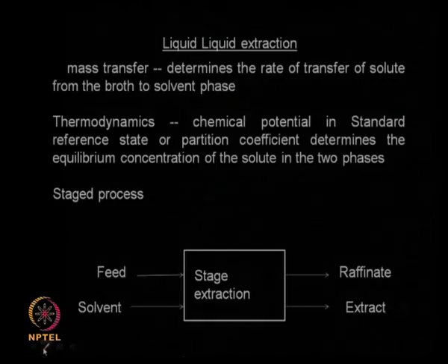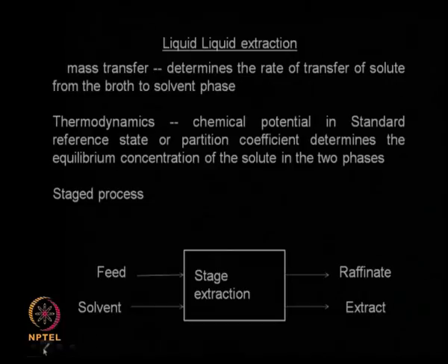The next one is the thermodynamics. Thermodynamics determines how much can be extracted, that means the maximum under ideal conditions what will be the maximum amount of solute that can be extracted from the fermentation into the solvent layer. So this particular parameter is based on the partition coefficient, or it is also called the standard chemical potential, for the particular system under consideration.